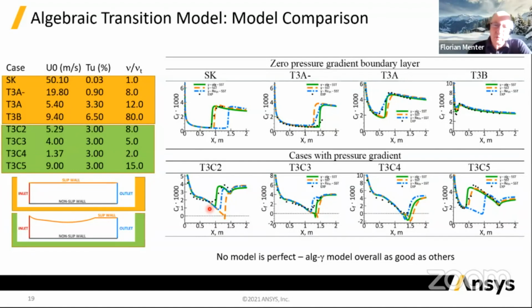But we could probably even calibrate them more closely. But sometimes it's better to have a bit of variation in calibration, so that people can use different models if one of the models doesn't do exactly what they want, or you could use the coefficients again to tune them. So we have a fairly cheap way to handle transition, which of course also for heat transfer problems we found to be very important.